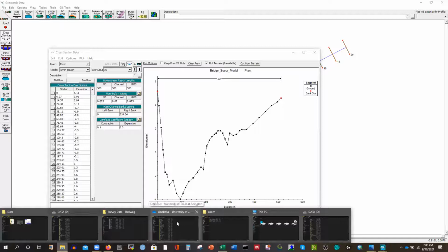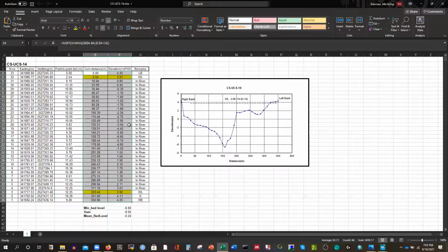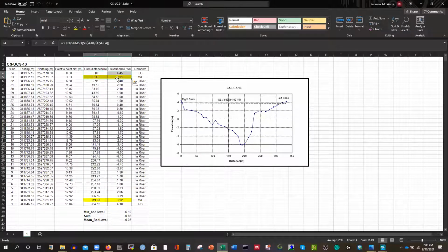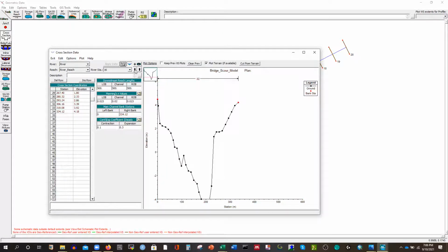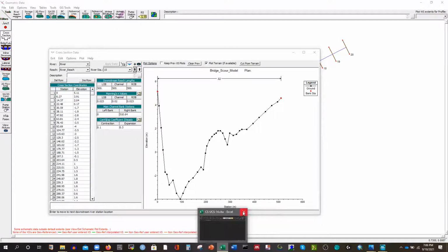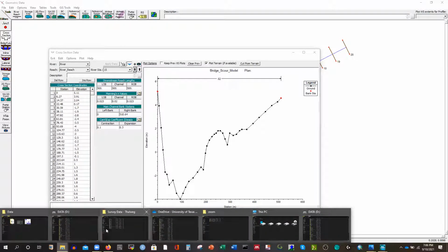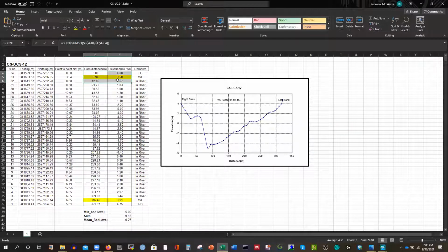And then our model, because we are just focusing on our bridge model, so we don't need to even worry about the cross section that are far away from upstream, only the survey data. Even we can use DEM data to create any model, but since it is a real case for a bridge design, that's why we spend money to survey this river to make our model perfect as much as possible. And you can utilize this one as well. This is your opportunity, I think. You can see and you can replicate. So these are the real world case.